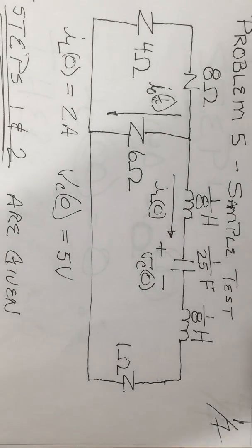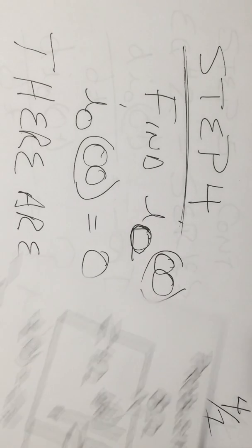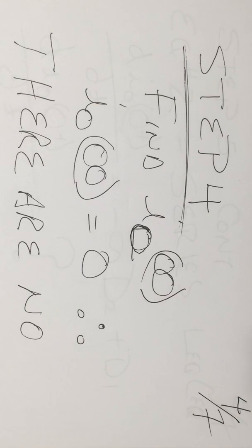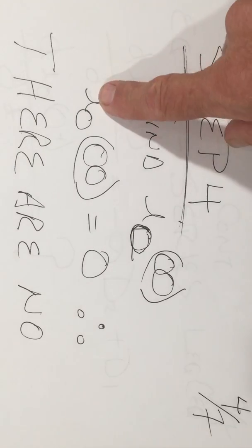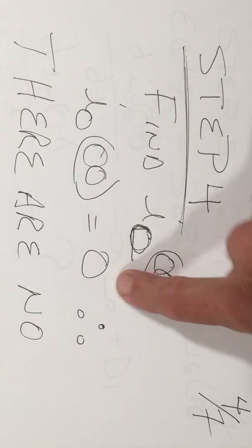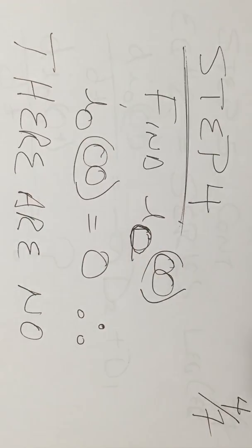So I know the resistors in the circuit are going to drain the storage devices of all their energy, and there won't be any current flowing in that circuit at time equal to infinity, 5 time constants later, quote unquote. So IO at infinity is 0 because there are no sources in that circuit. Now I'm ready to go to step 5.